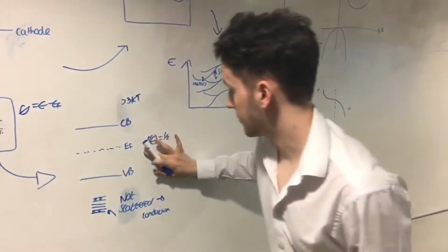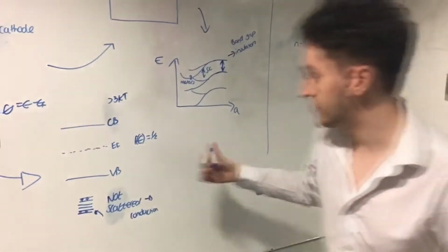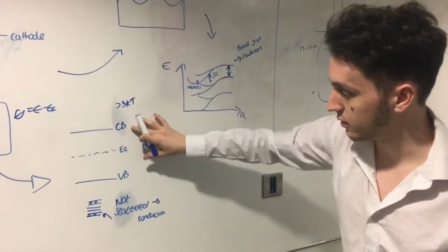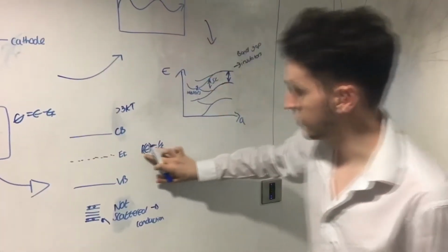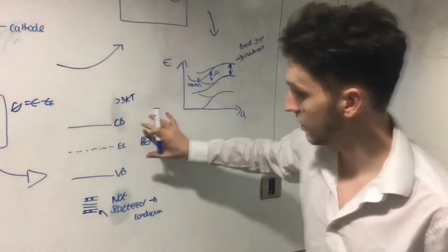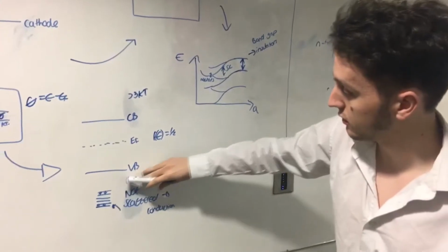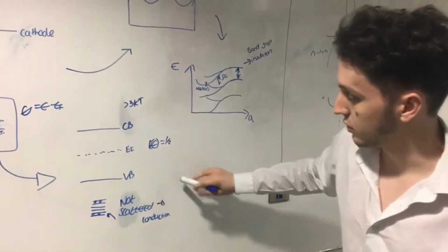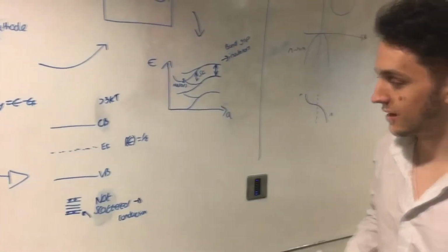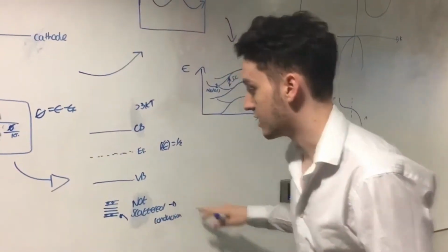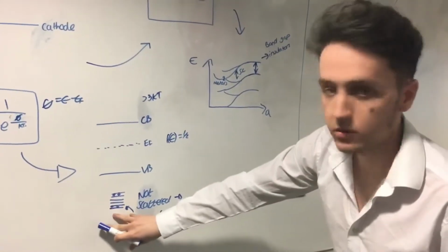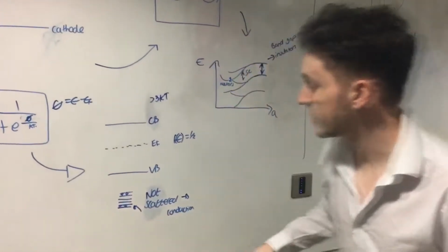So the Fermi level is an imaginary level at which the occupancy function is a half. It doesn't necessarily have to lie between the conduction and the valence bands, but it is always equal to half. At equilibrium, at 0 Kelvin, it is between the two bands. And generally conduction can't occur for any electron in the valence band because they're all locked into these finite states. And the Pauli exclusion principle means that they can't really enter any other state because they can't be scattered. Each electron can't have the same quantum numbers, like 2 electrons, and so they can't be scattered out of these states very easily.